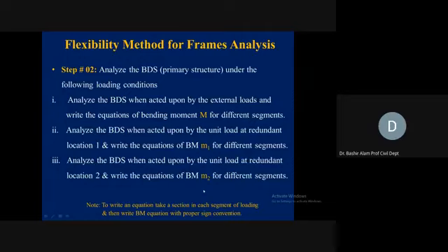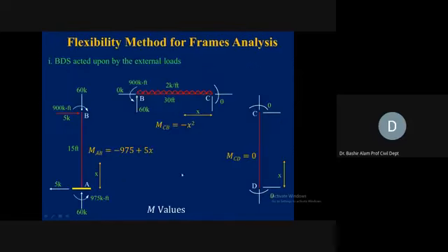So next now, this sign convention is also important. Here now, if you see, this is the same basic determinate structure. At A, we see the fixed support. This was a rigid joint B, so we have split this into 2 now. Still, it will transfer its actions. I mean, it can transfer the moment as well as the shear and axial force also. At C, we have opened the joint only. Rest, it is the same.